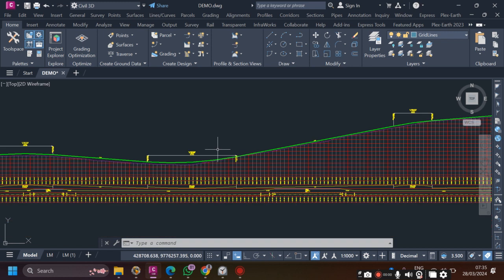When you talk of these two elements, the straight grade influences the drainage characteristics of that specific area, during both the design and operational stages. It also influences the construction cost, and the comfort of the road users. One rule of thumb is to avoid short grades between two successive vertical sag curves, because it gives an illusion of an optical hump. But we're going to get to that later on.